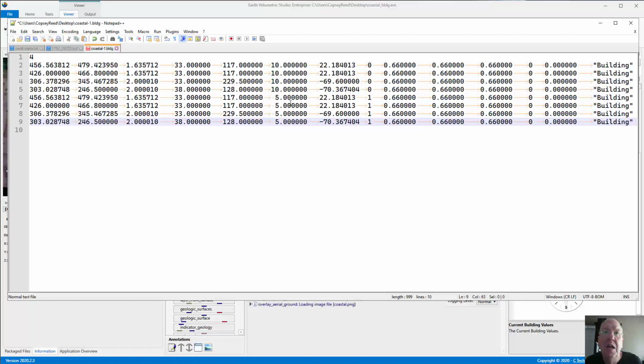And then the last thing I need to do is raise these up, because I don't want the bases of the roof to be on the ground. I want the bottom of these roof sections to be at the top of the buildings. So how high are the tops of the buildings? Well, this gets a little tricky, because you'd think, okay, buildings are 10, I would just add 10 to this. But remember that the z-coordinates here are scaled by 5. So we really only need to raise our roofs by 2, 1/5 of 10. So we're going to add 2 to the z-coordinates of all 4 of the roof sections. So this becomes 3, 3, 4, and 4.